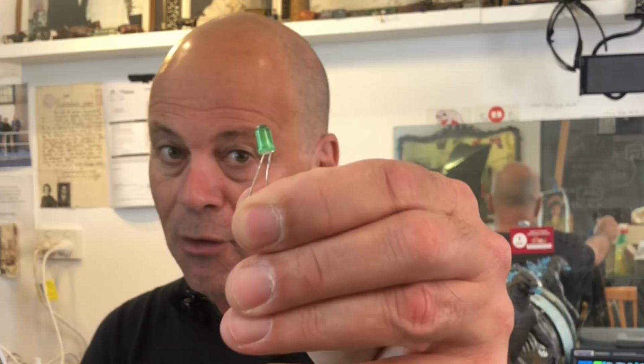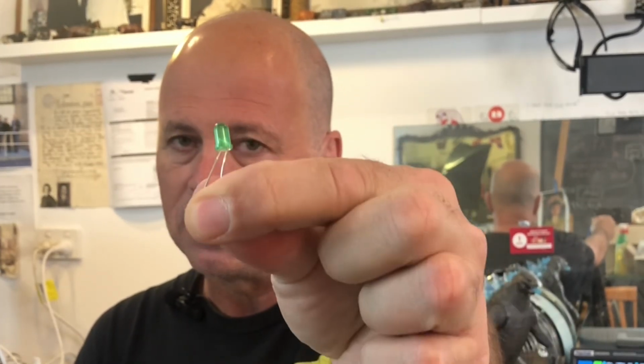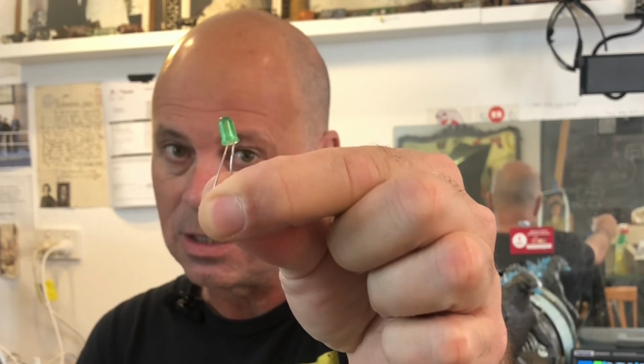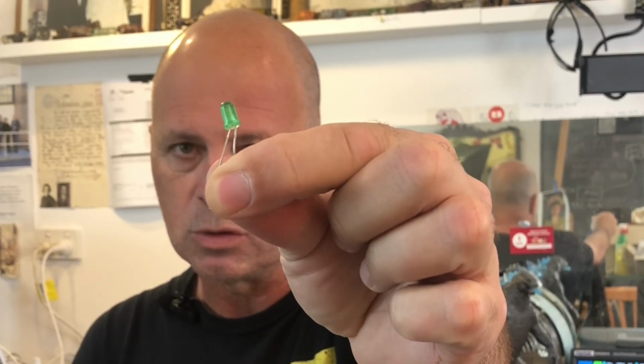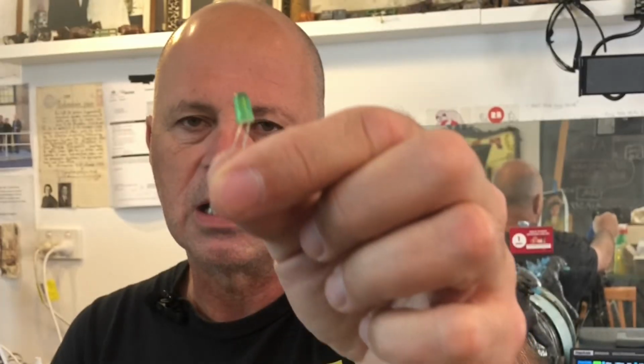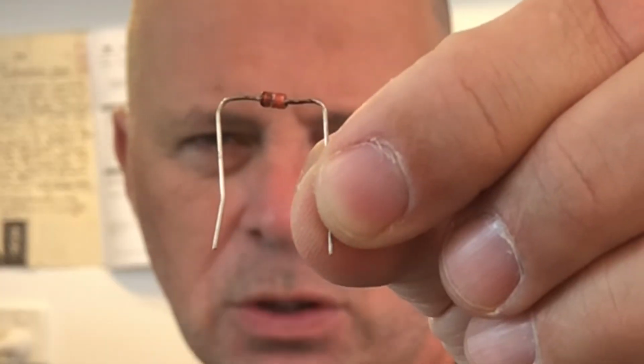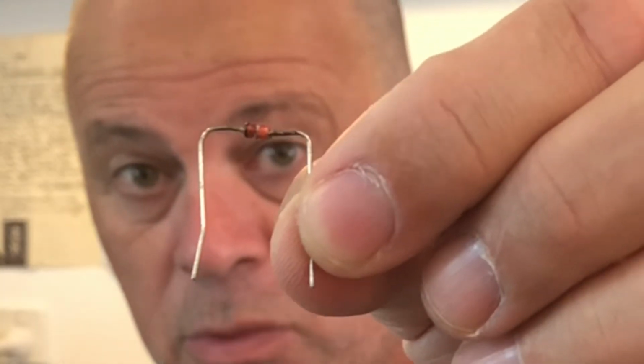Now, diodes come in all sorts of shapes and sizes and all sorts of flavors. They all have the one thing in common, of course, and that is that they allow current to flow in one direction. Some of the diodes you may be familiar with are things like our LED. LED is an acronym for light emitting diode. So it is a diode. It needs to be correctly polarized, which means the positive needs to go to the correct lead and the negative needs to go to the correct lead. And if it's connected correctly, it lights up. We also have small signal diodes that might be used as a detector in, say, an AM receiver.